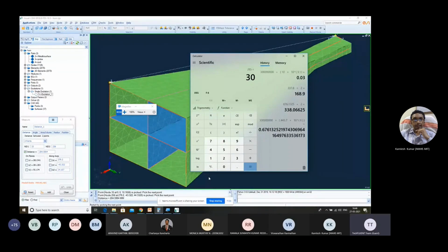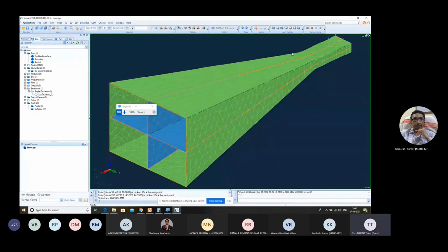So for this case also we can go ahead with MOM logic. If your antenna is more complex, like greater than 10 lambda up to 100 lambda, then you have to go ahead with MLFMM logic. This is just an approximate distance measurement that I've done here. It's a diagonal distance that I've calculated. It would be even less.